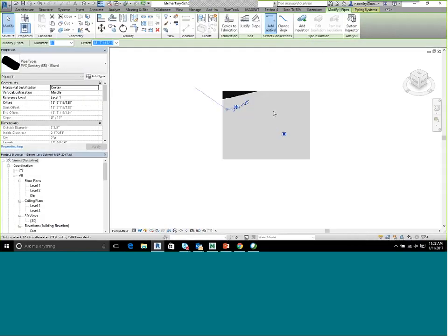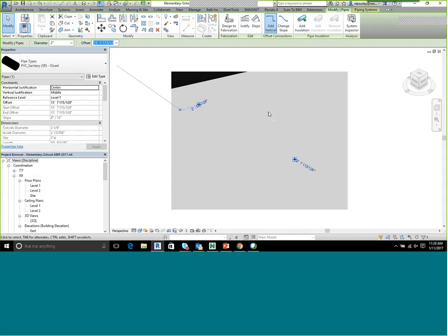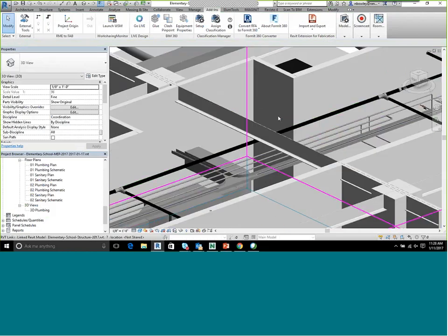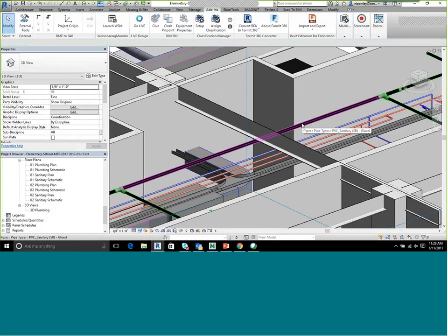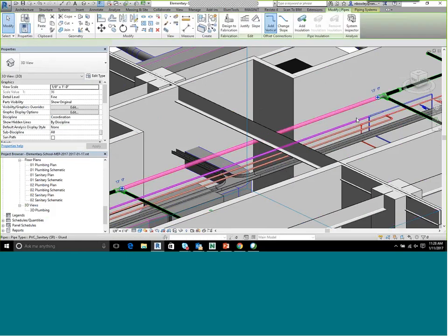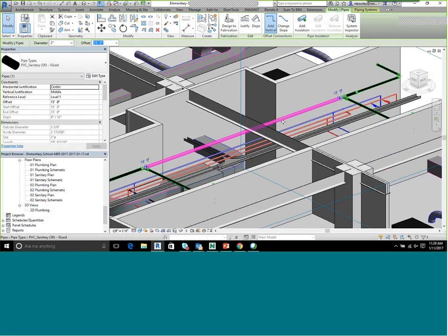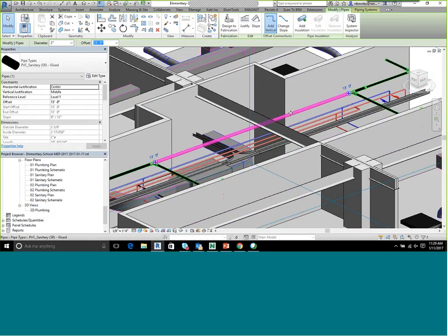All right, so what that did was it generated a 3D view of the object you had highlighted. Again, the reason I don't really like this tool is because I don't usually like what's in the view. If the walls were transparent, then I would see it. But the object is selected, and I do have my 3D view open that I like. So if I deliberately have the 3D view open, it'll generate that camera view, and I'll just hit Control-Tab and cycle back to my 3D view. When I came to that view, it was highlighted a second ago before I clicked. So that's how I typically use the tool. Again, for me, it's just as easy to do a search by ID and just be in the view I want to see it in to begin with.